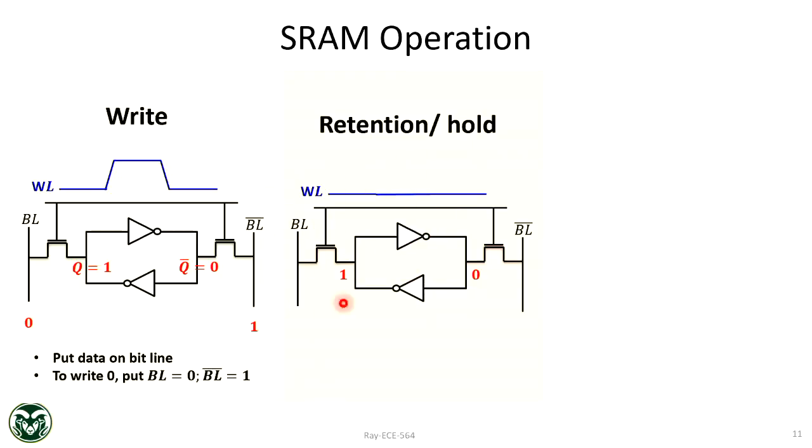And if you want to read the uninitialized content, then you just need to read without writing. Turn on the SRAM and read. Then you know what the uninitialized content is. If you want to write after that, you can write and that data will be there.